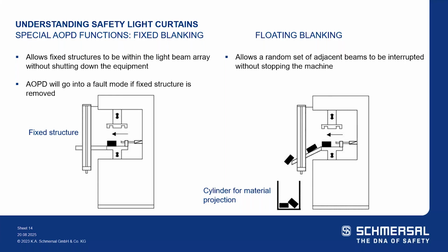However, with blanking, especially with floating blanking, you're effectively changing the resolution of the light curtain. So when you're introducing blanking into the application, new minimum safe distance calculations will have to be performed once the blanking and floating blanking functions are activated.